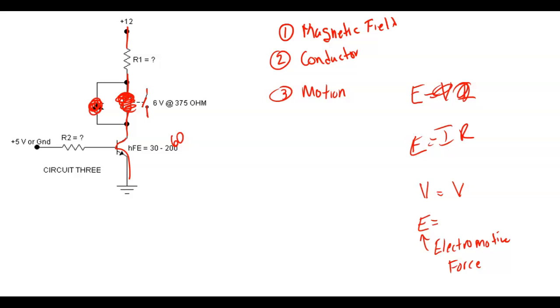Relay contacts are rated at a voltage. That's how much voltage they guarantee they can break. If you've got enough push, you're going to arc across almost anything. You see lightning all the time. There's nothing that's got infinite resistance, right? You understand? Well, the same thing is true with a transistor.